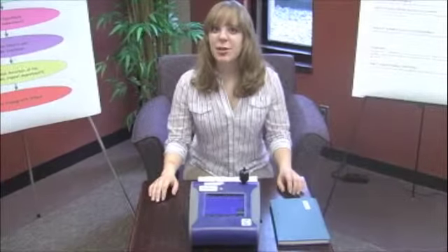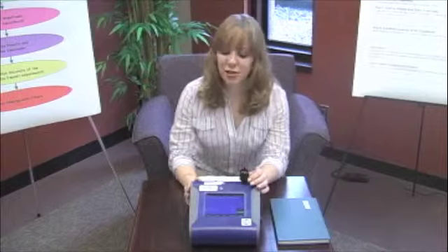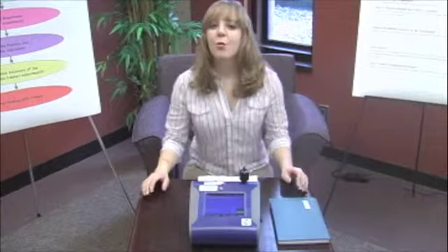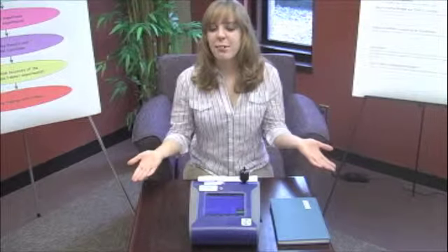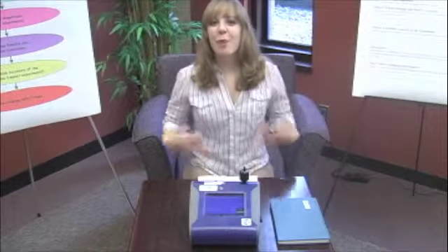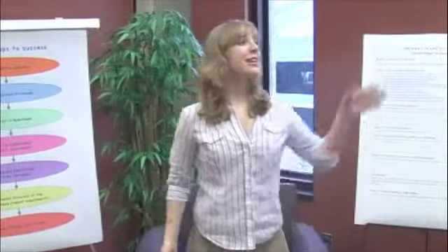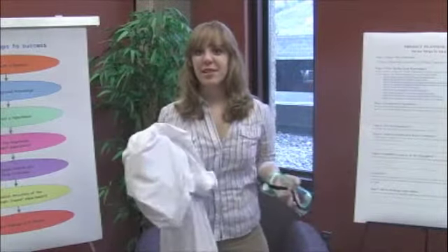In this experiment, we chose to study PM2.5. So, I chose the nozzle that measures particulates 2.5 microns and smaller. PM2.5 is of concern because particles of this size have the ability to bypass the body's defenses and travel deep into the lungs. Before conducting any real experiment, I always remember to put on my lab coat and goggles. Because as you know from your own experiments, safety first.